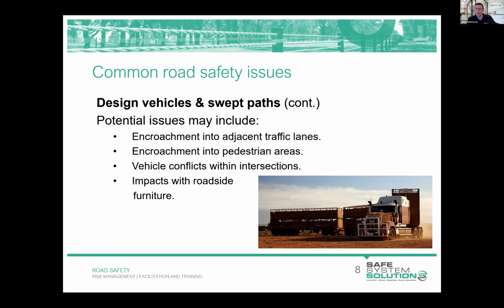Yeah, look, as an auditor, you wouldn't be doing those swept paths. If you're really keen and had those skills, you could. But in the first instance, you would request those from the client, and if they weren't able to be provided readily, that's a bit of a red flag. Swept paths should be undertaken as an integral part of road design, with intersections and raised islands and the like designed around those swept paths. So request those from the client.